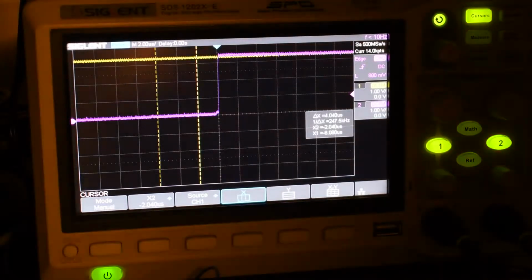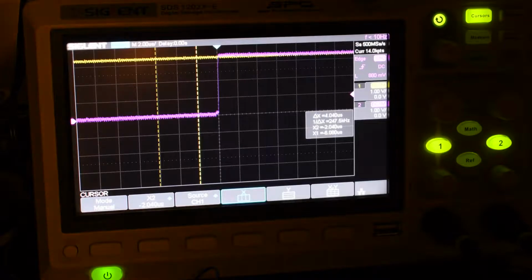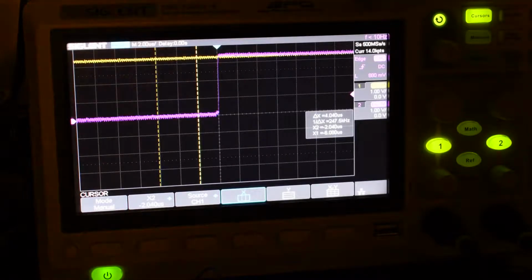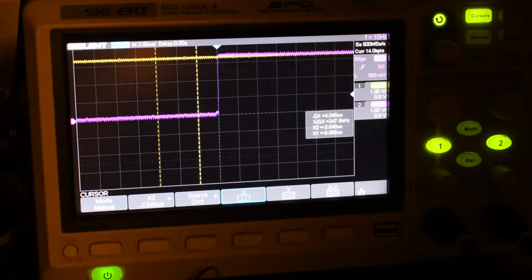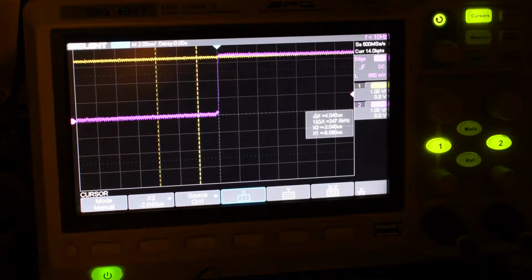So now I've got the two channels of the oscilloscope hooked up to the outputs of the two chains, and the inputs of the chains are hooked up, one of them to one of the GPS oscillators, and the other to the waveform generator, generating a 10 megahertz sine wave. And I hooked it up that way because the frequency difference is going to be a lot more obvious between those two than between the two GPS oscillators, so it'll be a little bit better for demonstration.